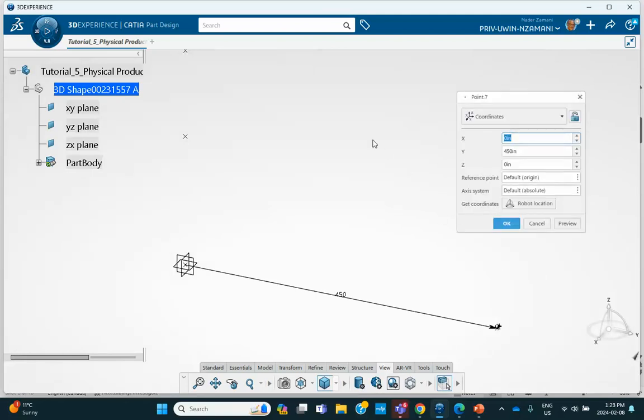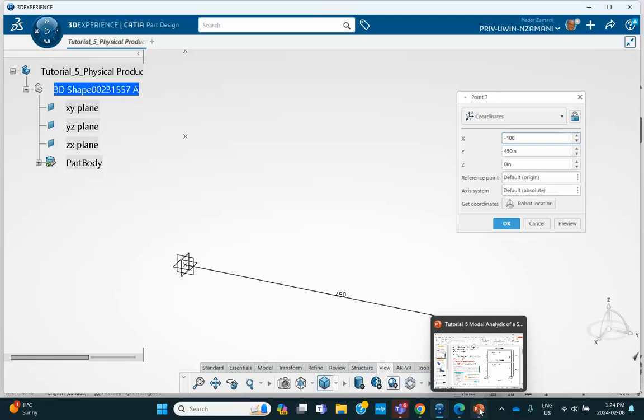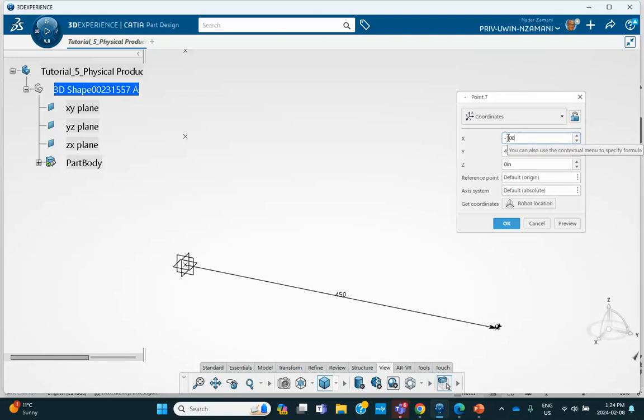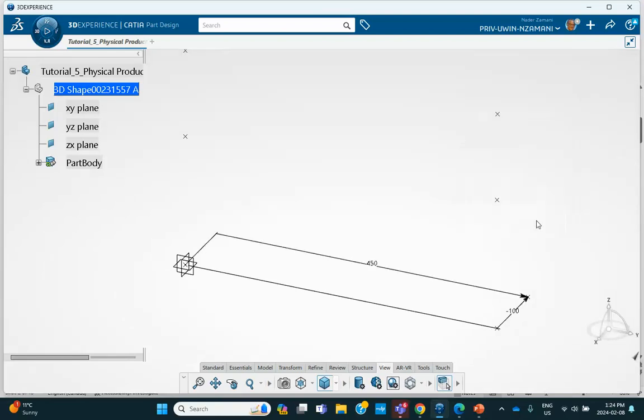Okay, so I've created the 6 points for the beam, and the seventh one I'm going to use for orientation. And I'll use a negative x in this direction, for example, minus 100. Now you can use plus. It's just that the coordinate system, axis 1, axis 2, axis 3 will be different from the one that's in ABAQUS, but it doesn't matter. In the first 4 tutorials for the orientation point, I used a positive value, which is on this side, but here it's going to be on that side. Cancel. So there we are.